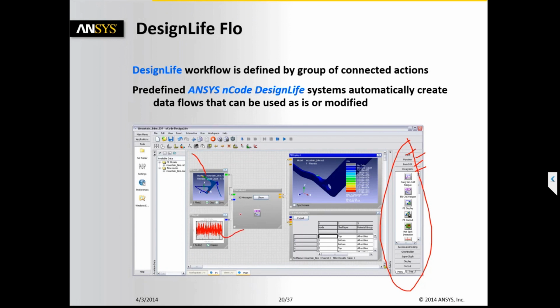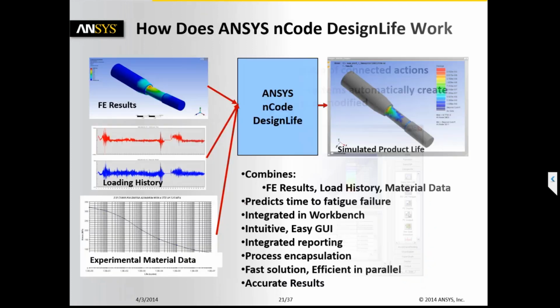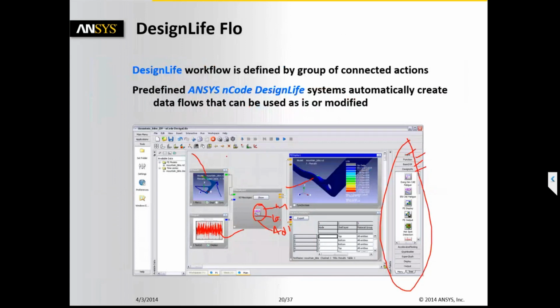And then the loads, the time histories you can apply and then perform the fatigue evaluation, where we will first map the material and then we will map the load conditions and then we will map, let's say, advanced settings where we will select what should be the mean stress correction equations, what stress values it should consider for calculating the fatigue life part. So this is the GUI of nCode.